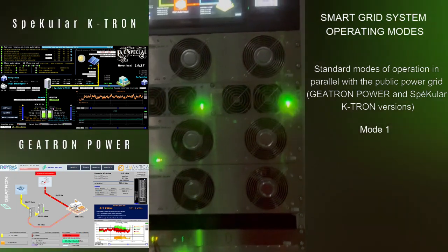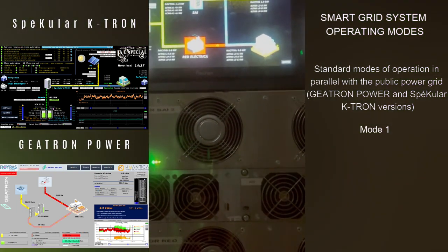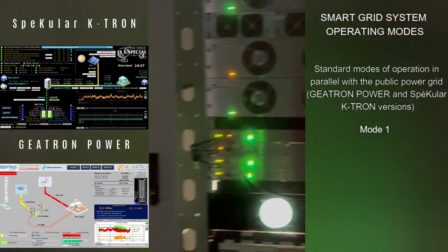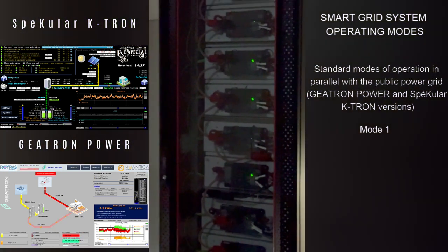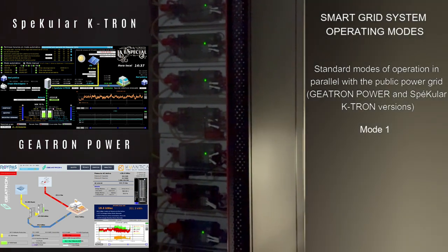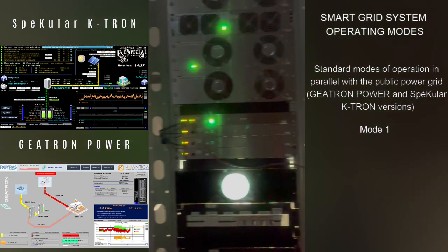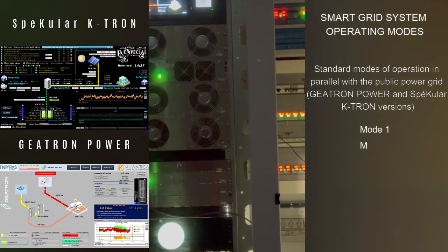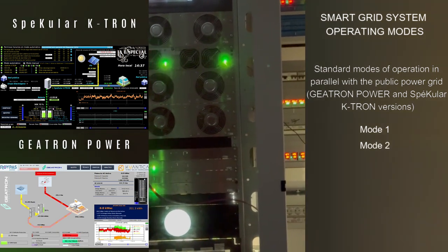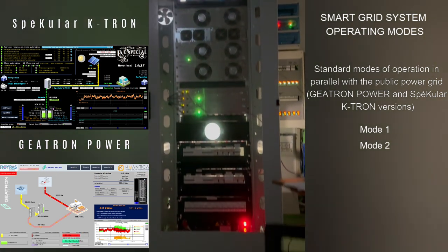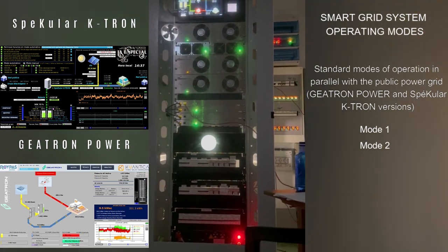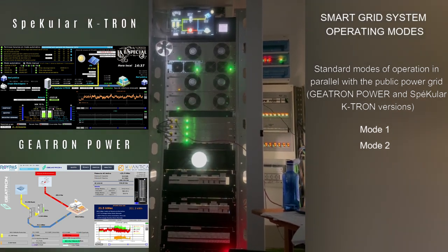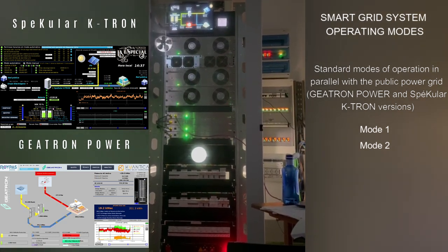Managing the battery to cover excess power consumption in relation to the power contracted from the power grid, while allowing for a reduction in the power contracted from the power grid. Managing battery recharging from the electricity grid, and managing battery recharging from the generator, if applicable. Mode 2. Parallel operation with the generator, supplying power to it when it is operating as an emergency system, thus providing greater autonomy to the generator's diesel consumption and supplying the generator's supply circuit with renewable power.